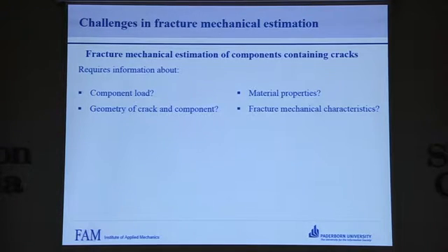So the fracture mechanical estimation of components containing cracks generally requires information about the component load, of course, and the geometry of the crack and the component, the material properties, and the fracture mechanical characteristics.